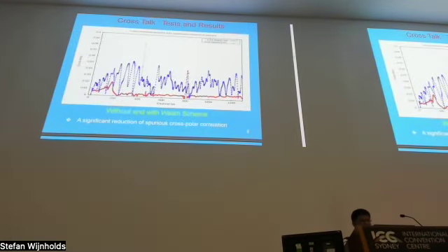So these are the test results. The blue line shows the crosstalk in C10 antenna, which was before Walsh implementation, and the red one is after implementing the Walsh modulation and demodulation. So there is a considerable reduction in the crosstalk.